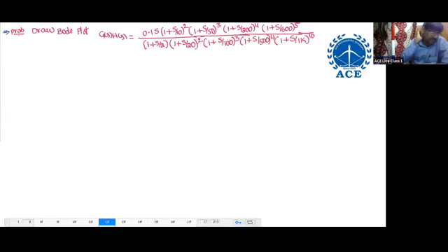A minimum phase system is an absolutely stable system. GH consists only of finite poles and finite zeros, that also only in the left half. Worst case, one pole at origin. That also, strictly speaking, you should not consider. It will come later. First draw the plot. Come on, first calculate M initial.